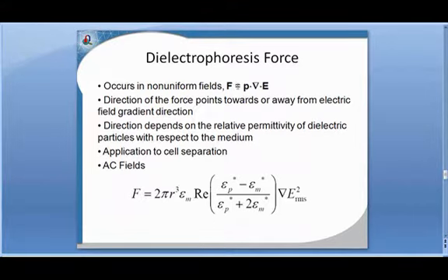As well, the dielectrophoresis force is present not only for static electric fields, but also AC electric fields. You might think that the time average force in an AC field will be 0, and that's not the case for a dielectric. There will in fact be a force, and it really depends on the relative permittivity of the medium as well as the conductivity. These are the complex conductivities, which in this notation include the electrical conductivities as well as the permittivities of the particle as well as the medium here. And this is the analytical formula for a single sphere in the presence of an electric field gradient.